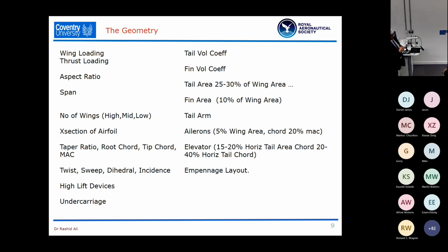Each has an advantage. Whilst you have a tail dragger, the pilot visibility out of the cockpit is not that great. So whilst we're taxiing on the tarmac, we do a weave to ensure that we're not bumping into things. But because the aircraft's already got incidence, they are interesting aircraft to take off. So those are the choices.